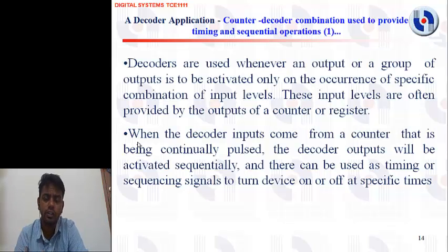When the decoder inputs come from a counter that is being continuously pulsed, the decoder outputs will be activated sequentially, and these can be used as timing or sequential signals to turn devices on or off at specific times.